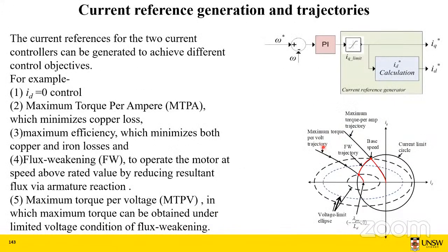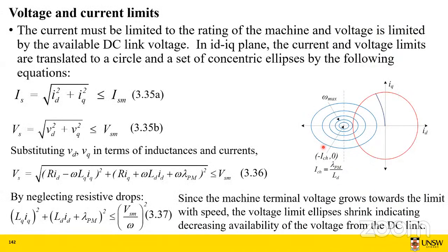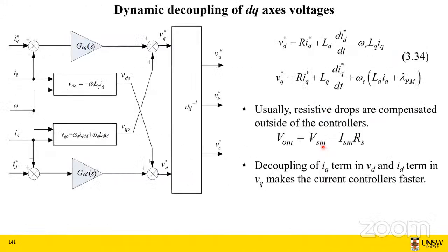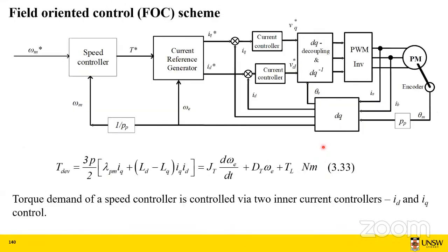And also the other thing to understand is that you may want to run the motor at certain operating conditions to get the optimum performance. So if you have the surface type PM machine, if you go back to our torque equation, in a surface type PMSM we don't have this component at all, right? LD is equal to LQ. The only torque component is lambda PM IQ.